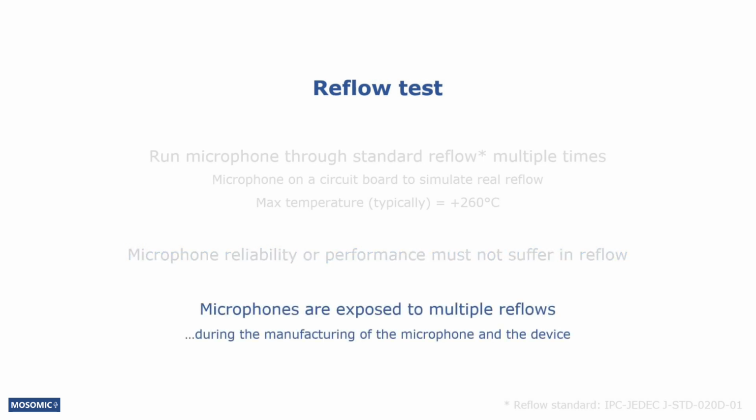The microphone and/or the chips in it can be exposed to multiple reflows during the manufacturing of first the microphone and then the device. It's not uncommon that the device circuit board goes through the reflow oven twice when components are assembled and reflowed on both sides of the board.